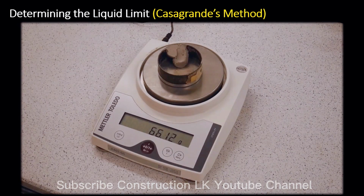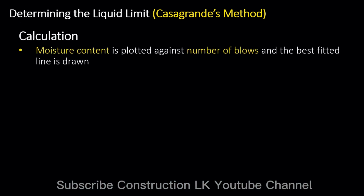We need a minimum of 3 samples. These samples will be based on the number of blows it takes for the material to flow together. Liquid limit is the moisture content of the soil when the groove closes with 25 blows. Therefore we would like to see 2 samples greater than 25 blows, and 2 samples less than 25 blows. Ideally all of them would be between 15 and 50 blows. Now let's see how the liquid limit is calculated from the test results. Since it is not possible to determine the moisture content exactly at 25 blows, the test is conducted as a multi-point test.